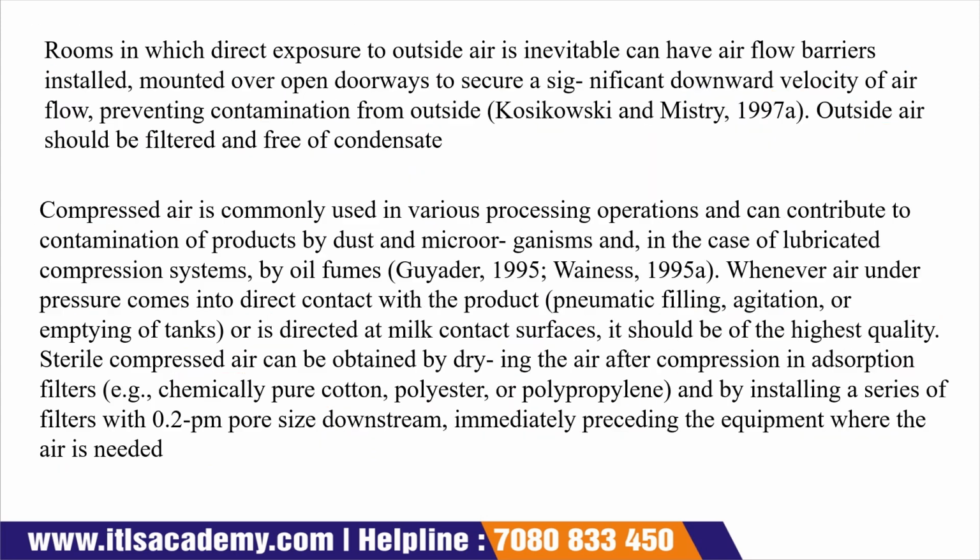Okay, now the next is a room in which direct exposure to outside air is inevitable. It can have airflow barriers mounted over open doorways to secure a significant downward velocity of the airflow, preventing contamination from the outside. And this outside air source should be filtered and free of condensate.